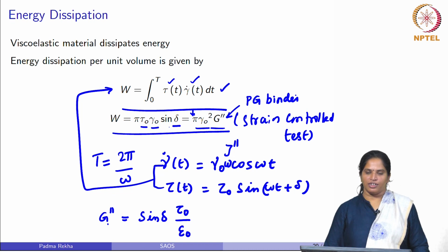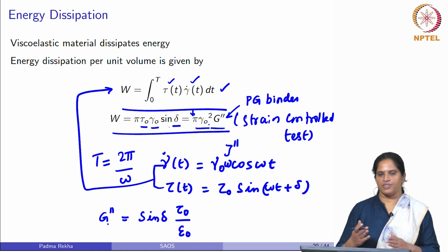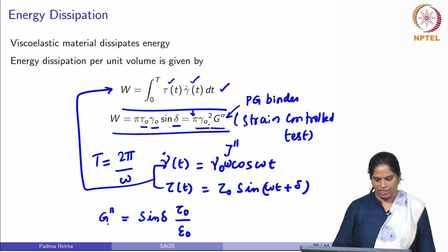Based on the energy dissipation, you can say when the pavement or the binder starts rutting or cracking, as energy dissipation varies with temperature. So, you can find the energy dissipation values at different temperatures by defining the tolerance limit. You can say that when the dissipation exceeds a particular value, the pavement fails in rutting, or when the dissipation exceeds extreme values at a low temperature, you can say that the pavement fails in fatigue cracking.